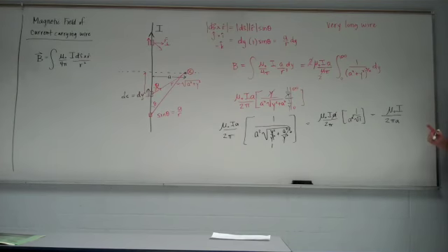So the magnitude of the magnetic field perpendicularly away from the wire: mu naught is a constant. I is how much current is flowing. So how much current is flowing determines the strength of the magnetic field. More current means bigger field. a is the perpendicular distance away from the wire. This equation will give us the magnitude around any very long straight wire. You don't have to derive it again if you have a problem that consists of a very long straight wire.